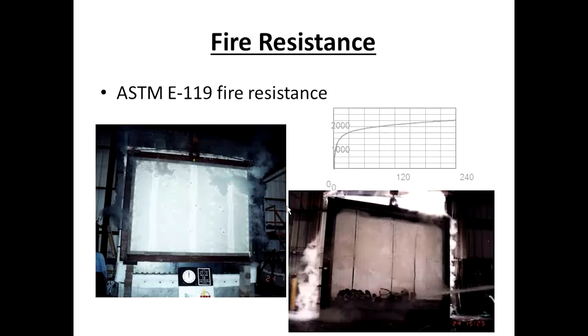We were building profiles maybe similar to this wall that you see here, and I would put them in a vacuum chamber, which would evacuate all the air behind it, thus putting a uniform load on the face of that wall, deflecting that wall to a point of failure. And the purpose of that test was to determine the contribution to stiffness that the wallboard provided.